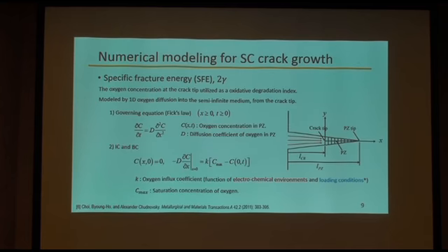Next is a decrease in the specific fracture energy due to the oxidation. The oxygen concentration at the crack tip is utilized as the oxidative degradation index in this study. And it can be modeled by one-dimensional oxygen diffusion into the semi-infinite medium from the crack tip.